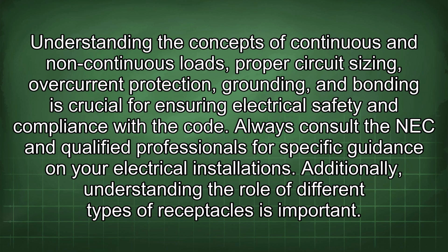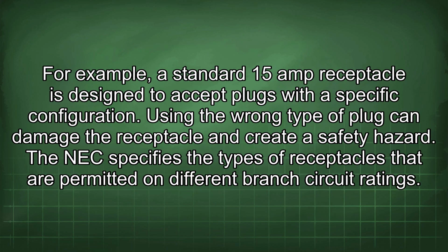Additionally, understanding the role of different types of receptacles is important. For example, a standard 15 amp receptacle is designed to accept plugs with a specific configuration. Using the wrong type of plug can damage the receptacle and create a safety hazard. The NEC specifies the types of receptacles that are permitted on different branch circuit ratings.